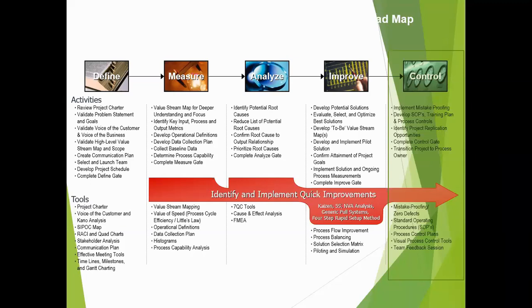We input the data in the system, and then based on the activities that take place, you generate the report, and it tells you. The system will tell you if you're within or outside the control limits. So it calculates by itself. Any unpredicted variation will be captured there. That's the whole point, special cause variation.